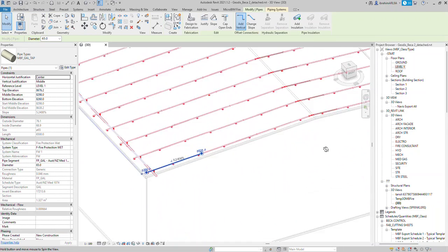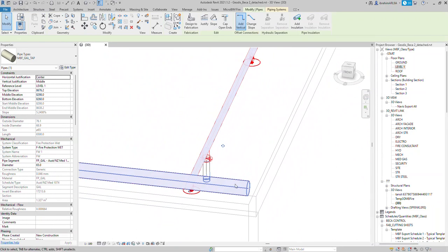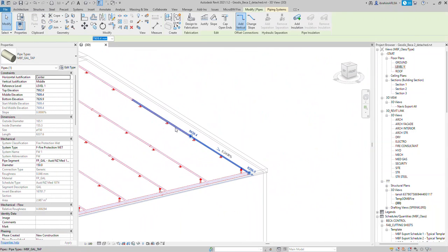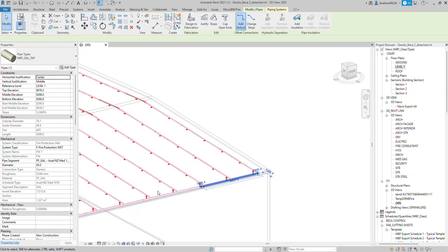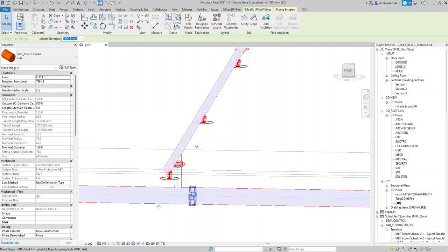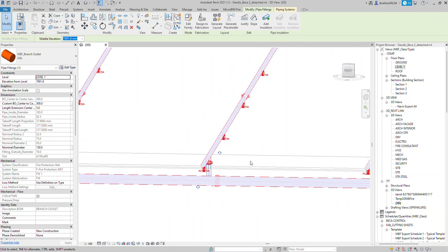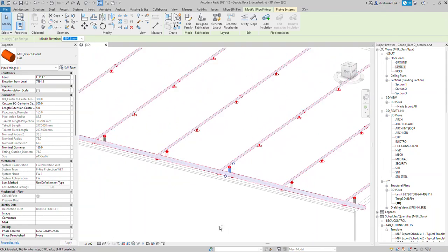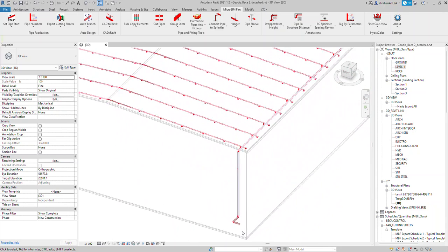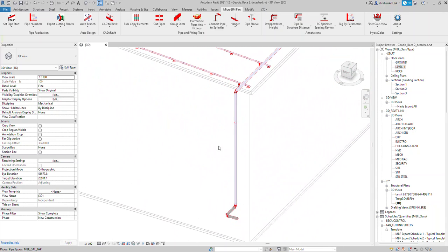Okay, so you get everything there. Everything is cut to the stock length. See the length in here, and the mains as well. This is smaller than the custom lengths because it will cut on an intersection here. That's why it respected the intersection by 150 mil and set back by this distance to allow the intersection to take place.